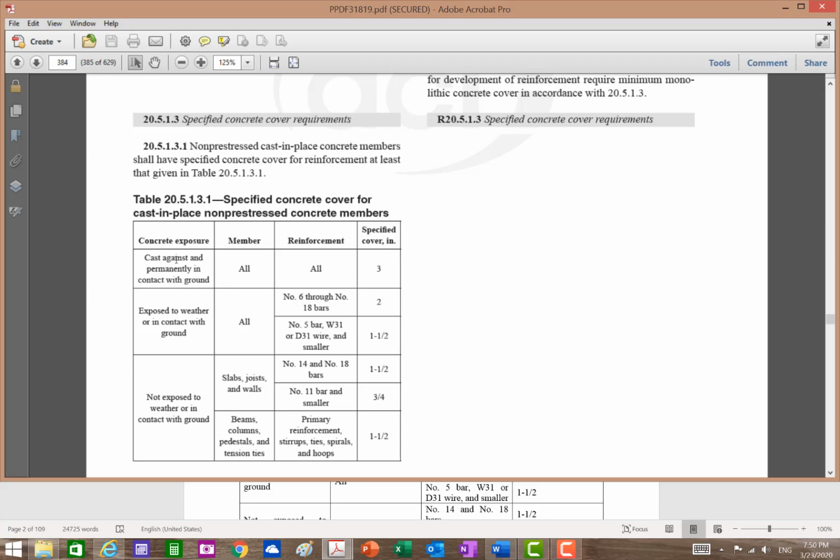Right? So the difference between these two then is, in the first one, the concrete is being cast directly into the ground. The ground is your form. Okay? In this one, you do have a form made out of wood or plastic or metal, whatever, right? You pour your concrete. Then at a certain point, when you've got enough strength, you remove the form and you fill the hole with dirt, all right? And then you make it to be in contact with dirt, and then you use this.